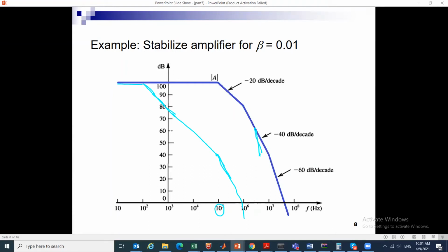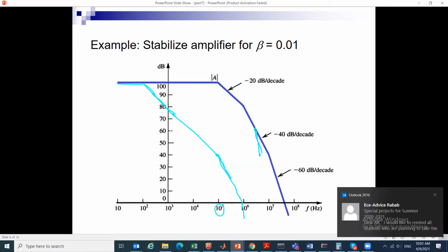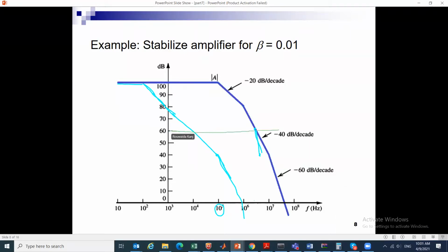And the phase margin. Last time, what we showed for this example is that the zero limit was around here, and that any 20 log 1 over beta which comes above this line leads to proper behavior and a good gain margin, and any beta that comes below it will lead to an unstable design.